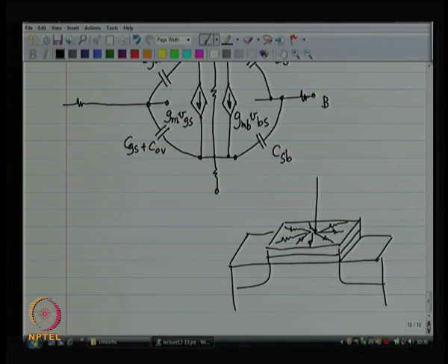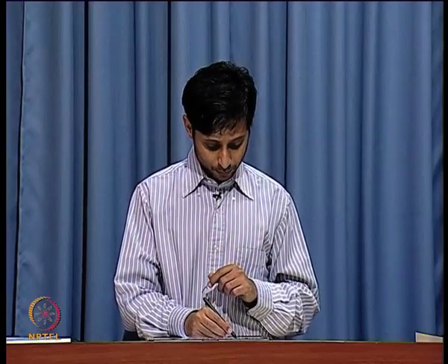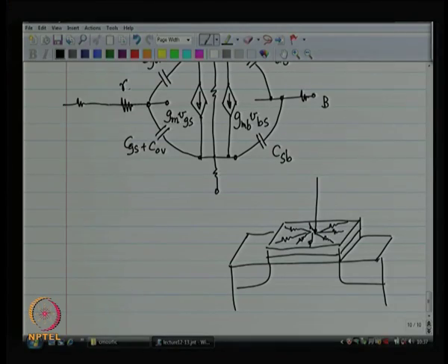In effect, you could think of the gate as a grid of resistors and corresponding capacitors, right. Now, such a distributed model cannot be accommodated, and it kind of depends on how you contact the gate, where you are touching the gate from, etc. So, we typically try to lump all of these distributed RCs together and we put something over here called the gate resistance.